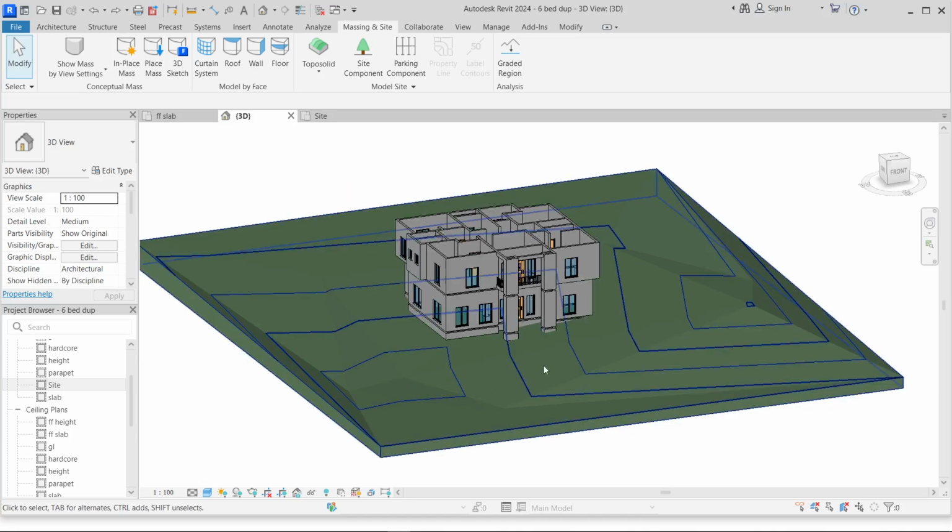So what does this mean? This means that all the runoff in this particular ground is going to be gathering at this point. Understand? So if you are designing, consider leveling this ground to an equal level, or consider installing a drainage here that is going to take out every runoff of this particular land.